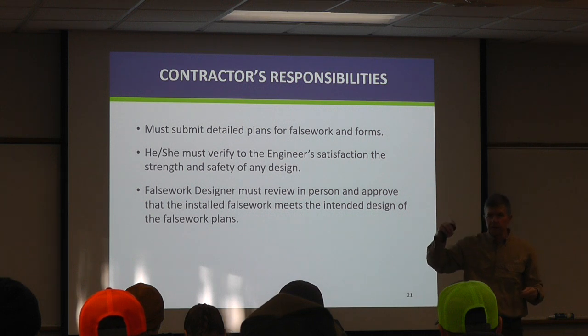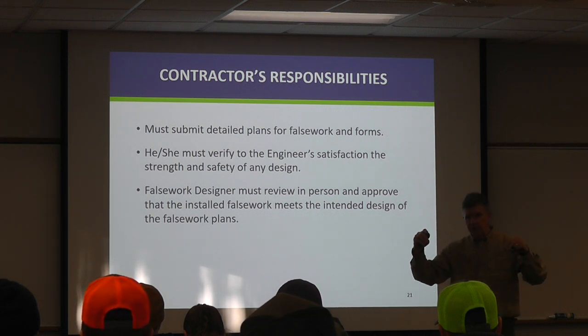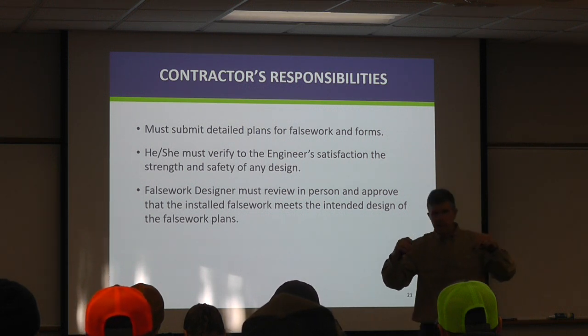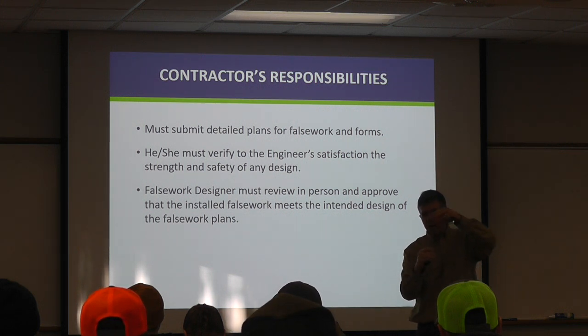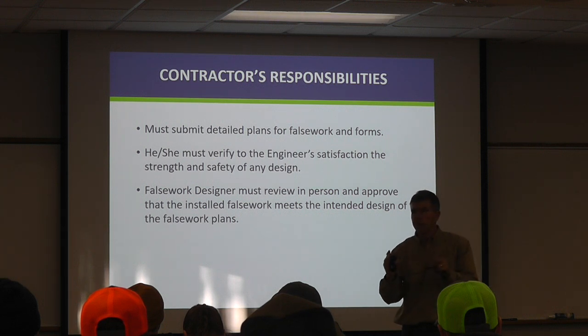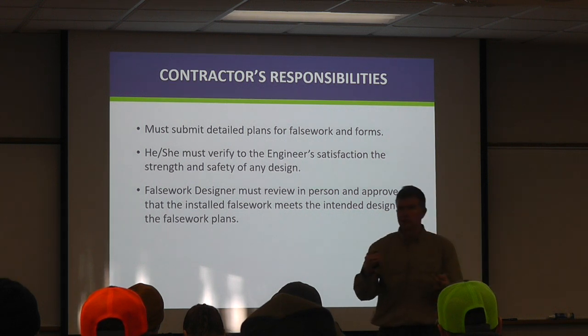Steel beams can be very good in bending. They can be good in tension. They can be good in shear, but in this case, a lot of load was coming right down through that little member, and there were not enough shear stiffeners to stiffen up that web, and so everything collapsed from that member.